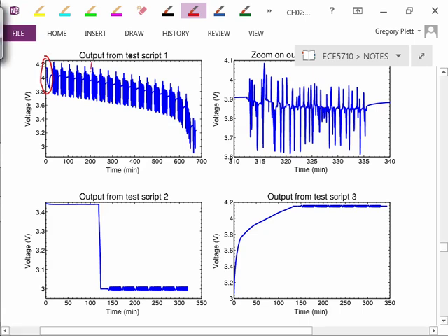And then each one of these squiggly parts of the curve corresponds to one UDDS test. I've done 1, 2, 3, up to 18, about 19 of them. That 19th one aborted early because it hit an undervoltage condition. In my case, I scaled them to be about a 4% discharge per cycle. You do 19 of those, it's about 80% discharge.